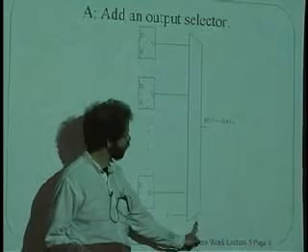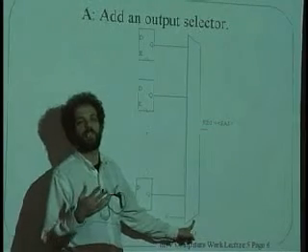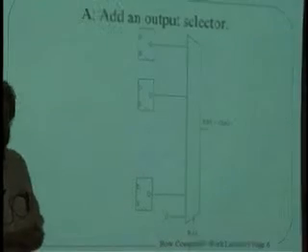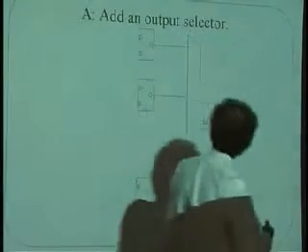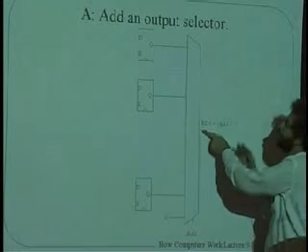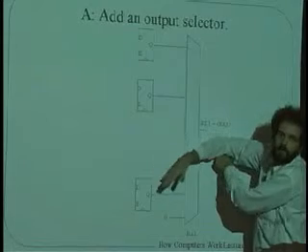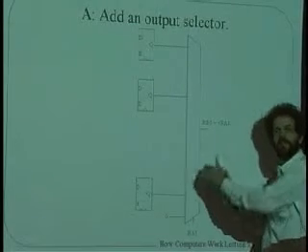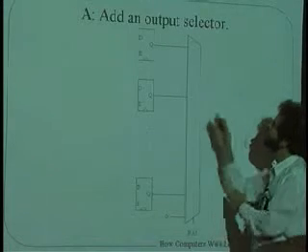And into the control input of the selector come 5 bits. And they specify one of 32 possible combinations. And those combinations each stand for selecting as a data item to be steered to this output, RD1, one of the 32 possible registers. Okay, if you remember the selectors we used before to steer how the data moved one way or the other inside of the circuit, this is the same thing.